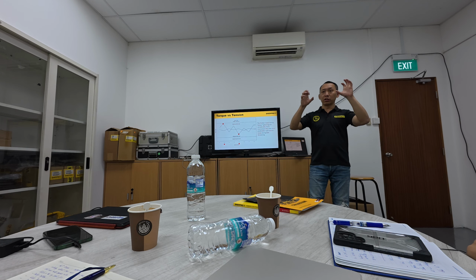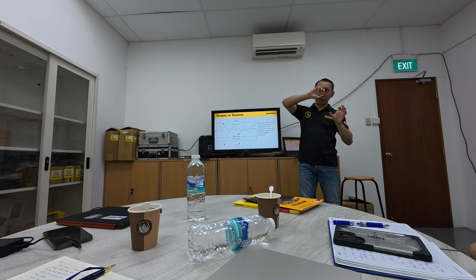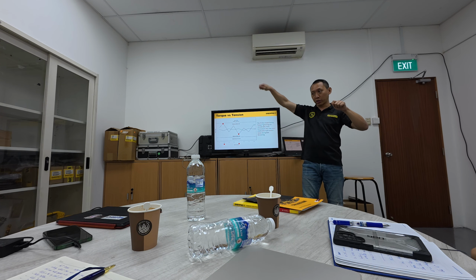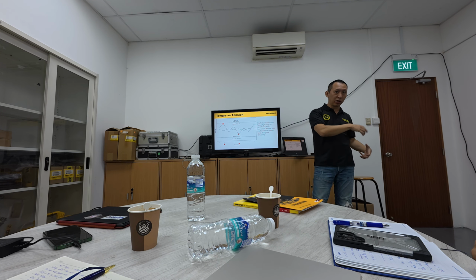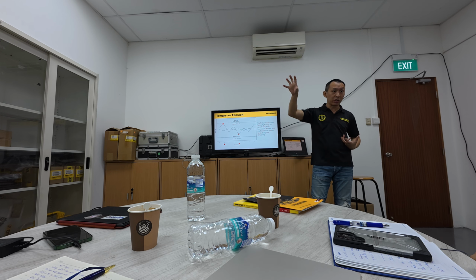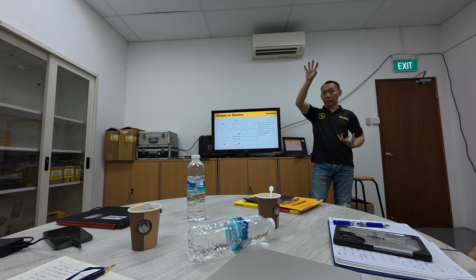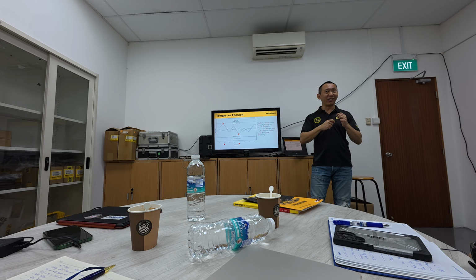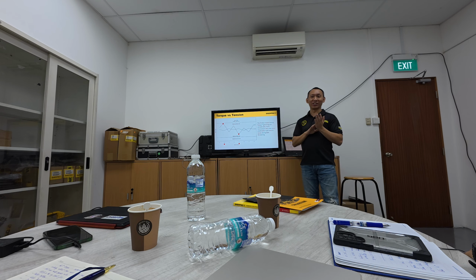For a tensioner, you need to set up, tighten, and mark it at 100%, 200%, and you need to connect many hoses and things. You need to know the operation sequence, the method statement. How much to set first: 100%, 50%, 25%, first pressure, second pressure. All these you need to know. So it's not so straightforward.